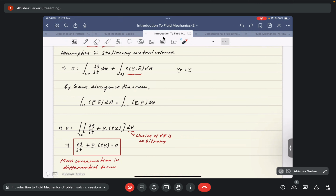And given that this choice of the control volume, or this elemental volume over which we do the volume integral, is arbitrary, the only way that this integral is 0 is if the integrand is equal to 0, right? That is dou rho by dou t plus the divergence of rho V is equal to 0. Okay, and this is the mass conservation in the differential form.